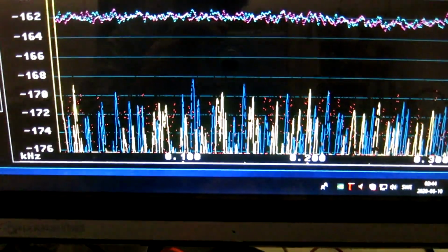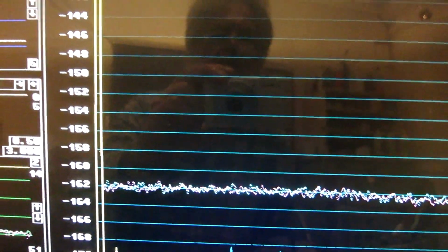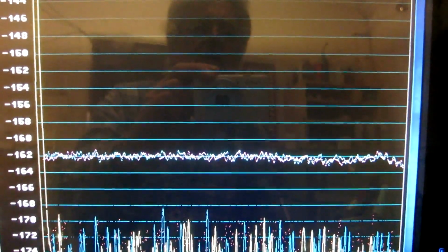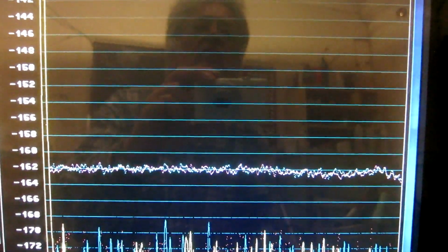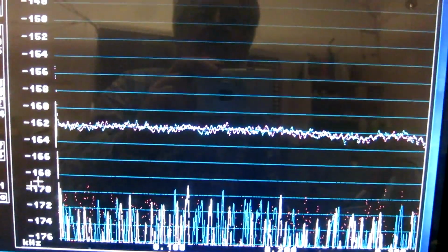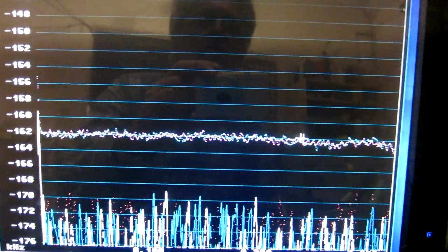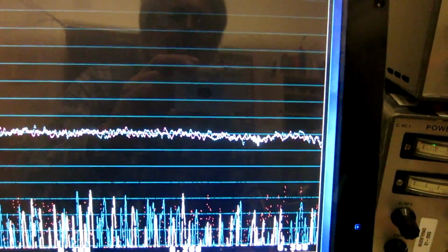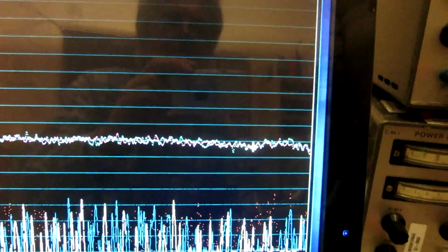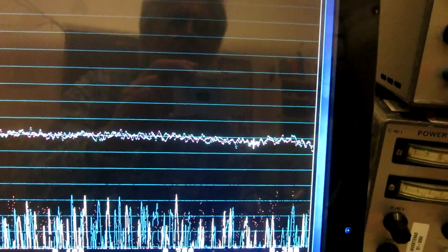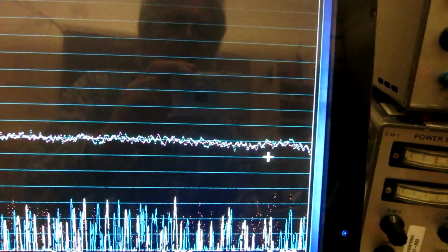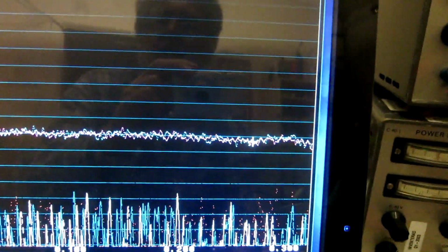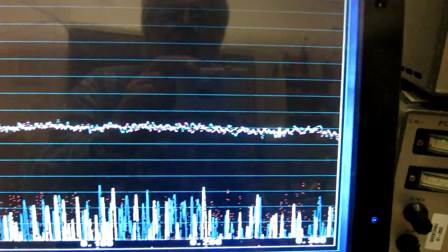And of course correlation is very low, there is no correlation, these are random numbers. But this is the demodulated phase noise. And here is the demodulated amplitude noise. It goes down a little bit here and then up here. There is some artifact in how filters are applied. There is a filter going down and there is a correction added, and there seems to be an error of half a dB or something.